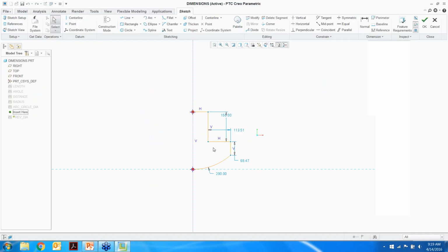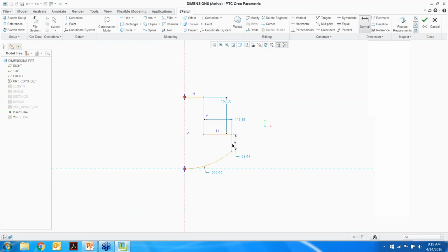In this case, we have our sketch created. The requirement for this one is that you need to have a center line within the sketch. So by selecting your dimension tool, you select the reference that you want to dimension, you go up to the center line, and then you come back to that same reference that you want to dimension. When you middle click, this will give you that revolve diameter dimension right here.